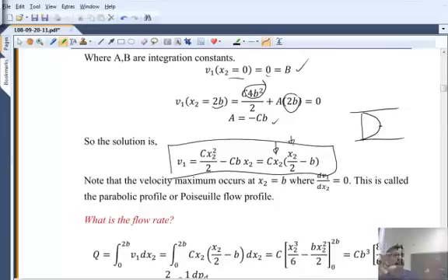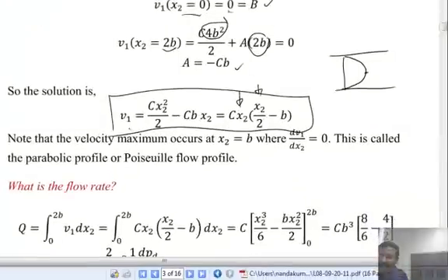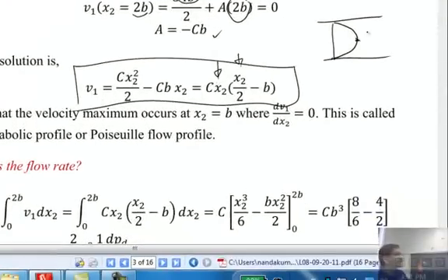Now, I don't know whether all of you are following the discussion that I just posted on the forum. There was a question from Chad, I guess, about when does the momentum flux peak, or when does it become 0? So in this case, you can notice that at the center point, the velocity gradient is 0. If the velocity gradient is 0, what can you say about the diffusive flux? What is diffusive flux? The shear stress. What can you say about the shear stress at the middle point? 0, because it depends on the velocity gradients.